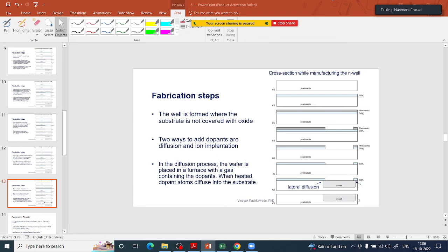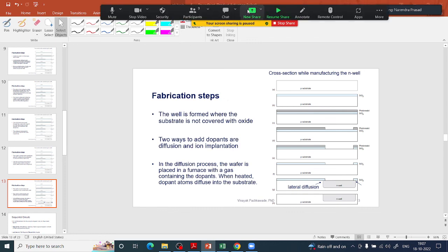Sir, we cannot construct a pass transistor only with NMOS, no sir. It's possible. See, what is a pass transistor? It is passing some logic. Again, let me make three sentences. It is passing whatever the input is there, same in the output without degrading, either 0 or 1. Correct. NMOS is good for passing a good 0. PMOS is for good 1, but not the opposite. Yes, then we need both the transistors. Alone PMOS it is not possible, no sir. Yeah, that's what I said, right?